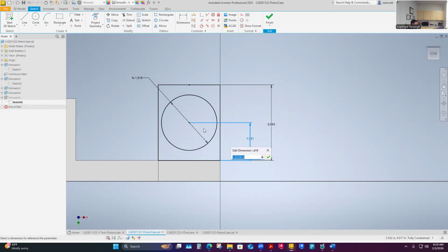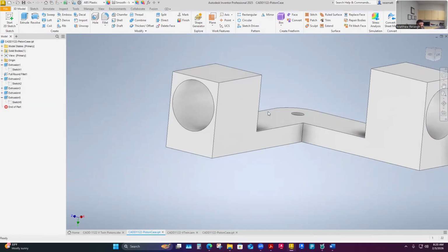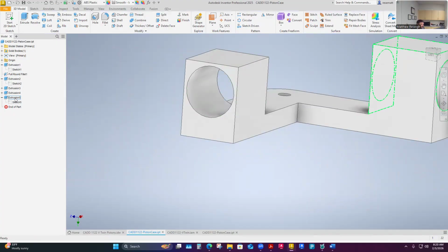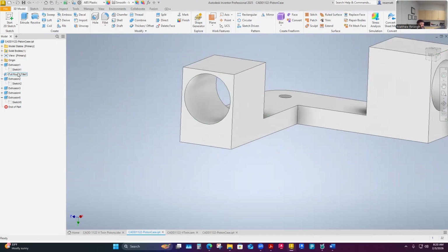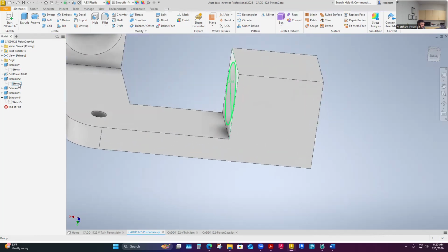I know that's a lot of decimal places. That's actually only 1/32 of an inch, 0.03125. It's actually a pretty common decimal fraction, even though it is out to 5 decimal places. So I think I'm going to carry 5 decimal places on that placement on my drawing. So I'll finish that. And then this one here, and this is arguable whether I should or not, or just carry 4 decimal places or 3, but there's definitely some rounding going to happen if I don't hit these dimensions.